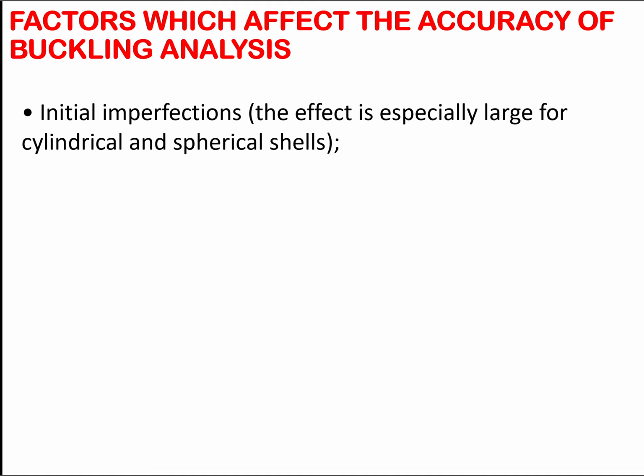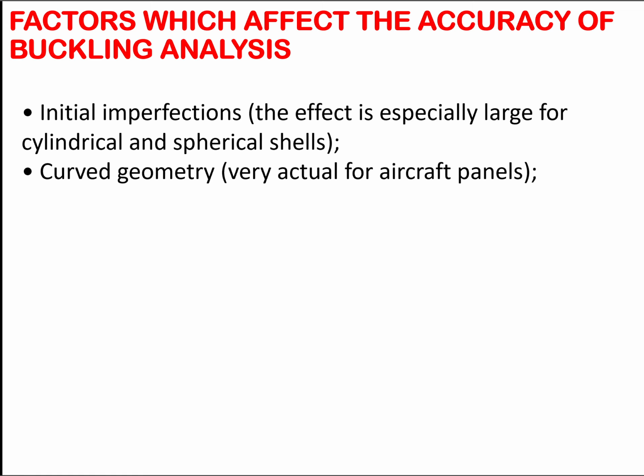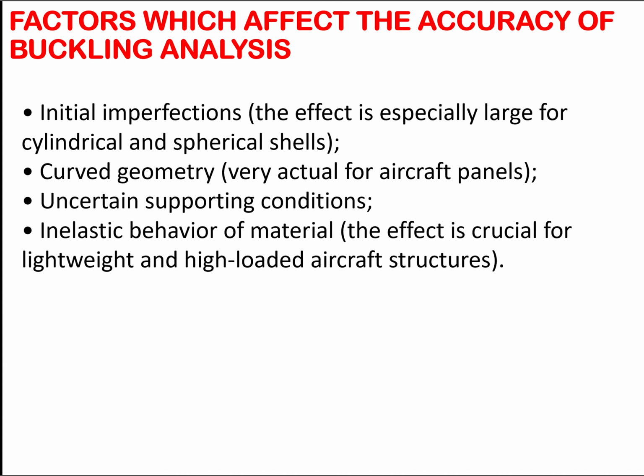But what makes plate buckling difficult? The initial imperfections that we need to include in any analytical model. Curved geometry always makes any analytical modeling analysis basically impossible. And also, whenever you are moving from a one-dimensional or two-dimensional rod or column to a three-dimensional space, understanding the supports that are necessary for your analytical analysis is going to be difficult.